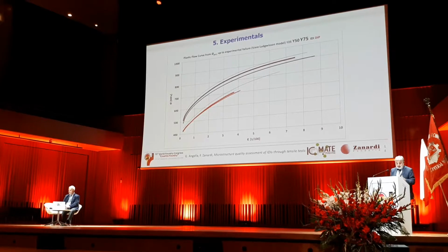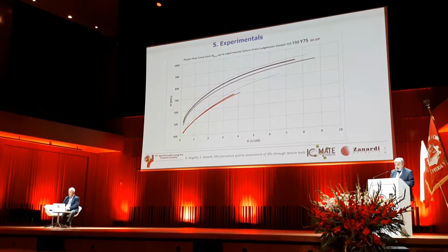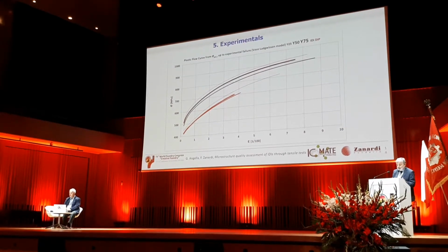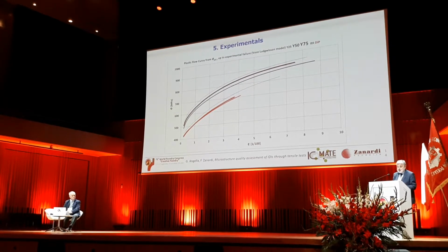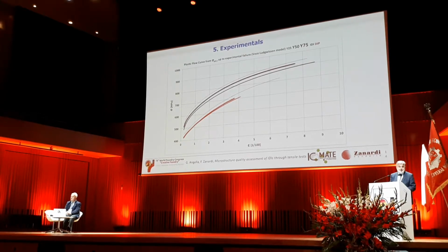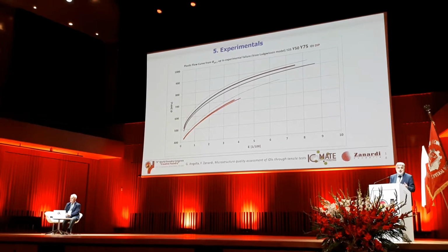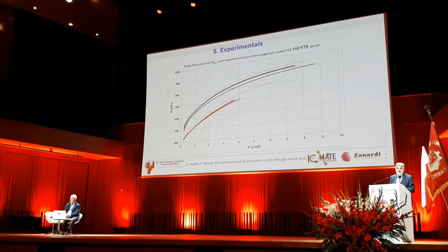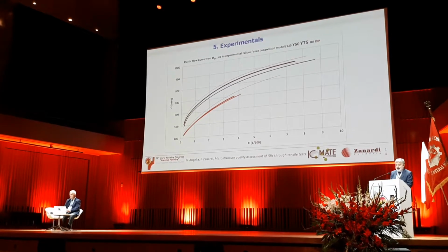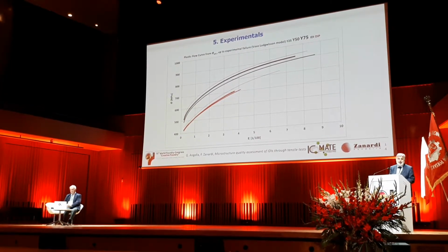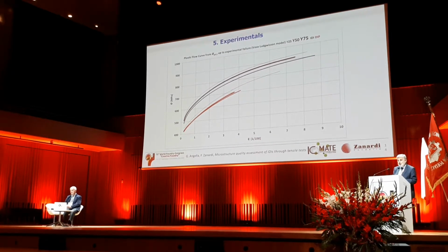This is the true plastic flow without the elastic component. You see how the effect of no segregation, no alloy, no addition is very important as the thickness is increasing. This is a demonstration that this material, IDI, is a very good material when you have non-uniform thickness castings. You can have a different thickness and get approximately the same properties all around the casting. It is the only way we know now for the ferritic grades.